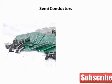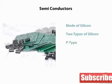For the most part, active components are made with silicon. Active components made with silicon are called semiconductors. There are two types of silicon used in the manufacturing of semiconductors. One we call P-type, and the other we call N-type. P-type silicon has a shortage of electrons in its molecular structure. N-type silicon has an excess of electrons in its molecular structure.